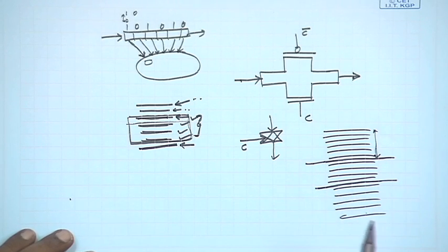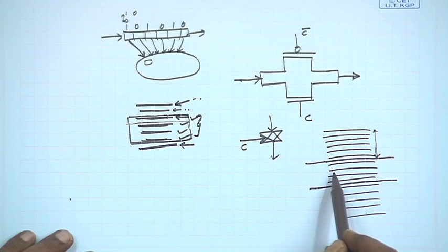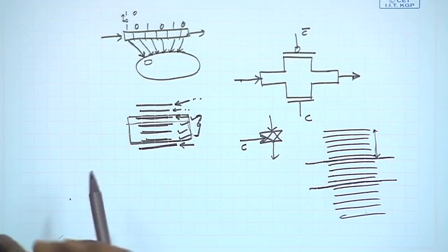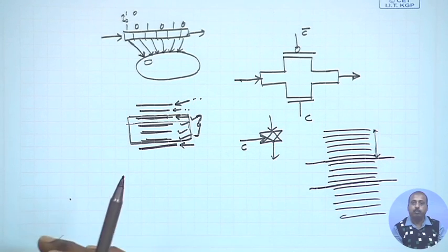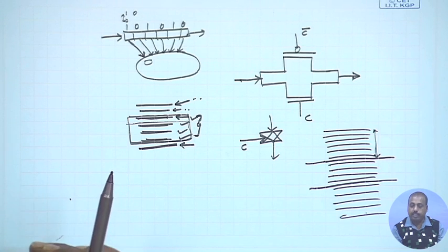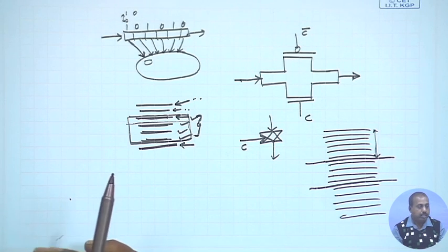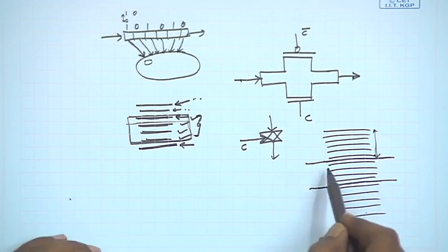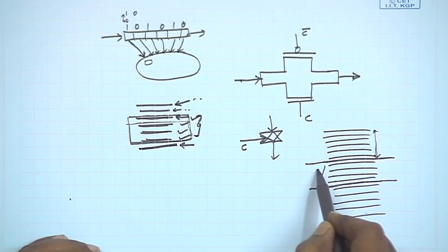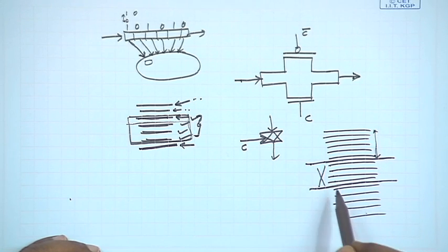In the previous case, the BIST filtering case, these filtered patterns were not allowed to appear at the circuit input, but the LFSR was generating these patterns. Now, in this reseeding approach, we do not generate these patterns as well. Rather, after this, the LFSR is reseeded with this particular value.